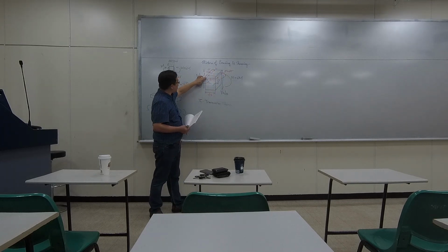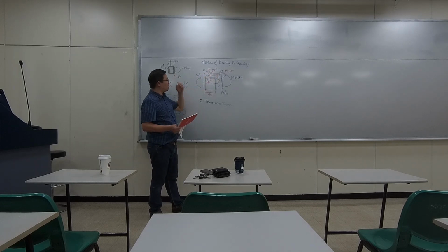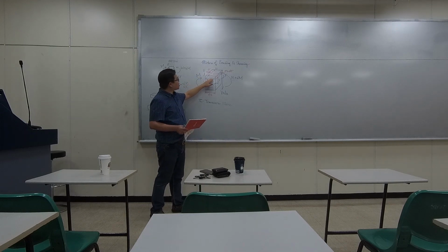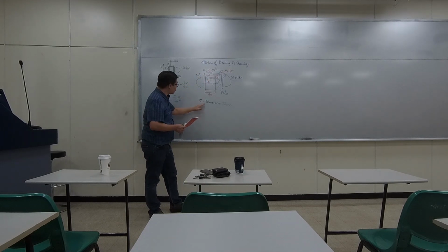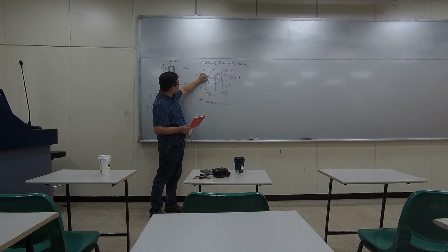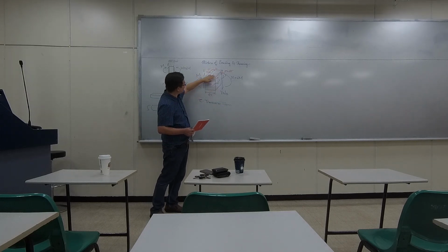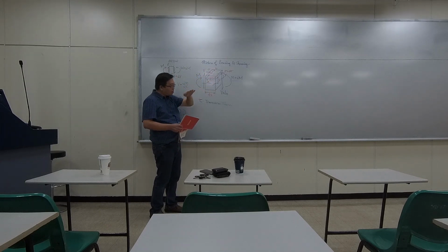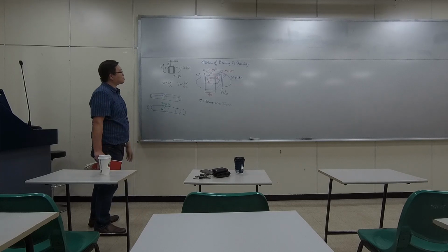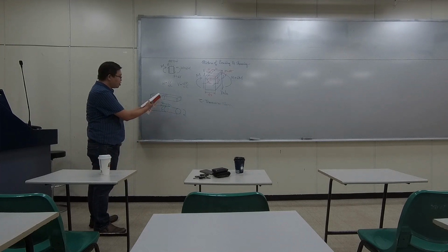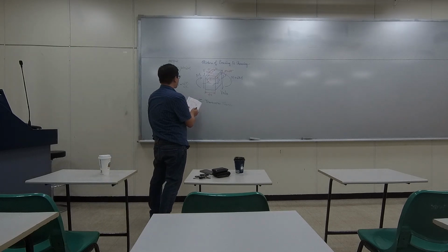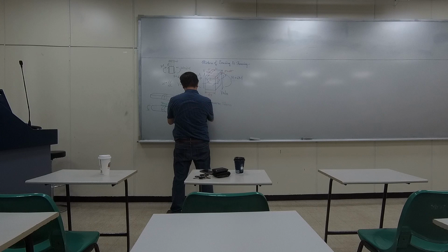And if you only observe this cut, at the bottom there could be shear. So when we talk about transverse shear, it's about this cut, right in the middle between the upper part and the lower part on that green plane. Okay? So if we try to do a force balance, we get something called Fn, Ff.